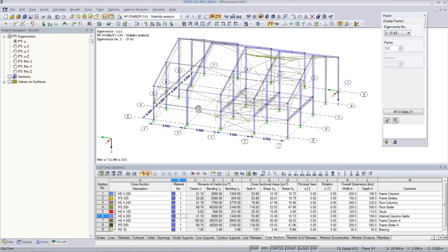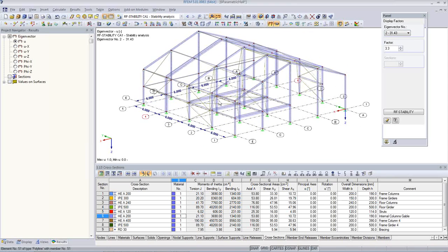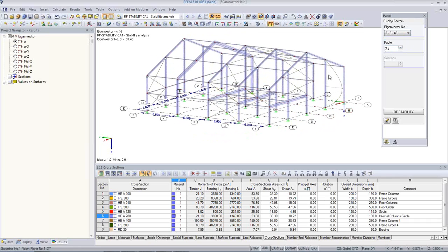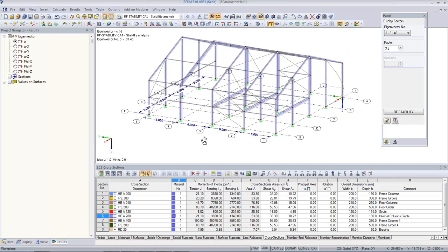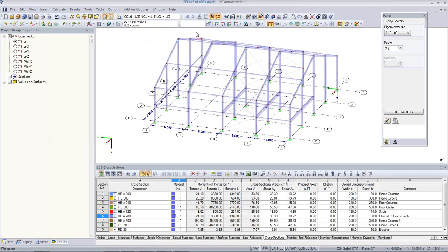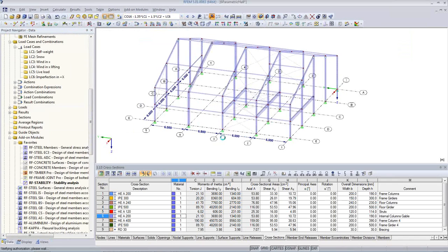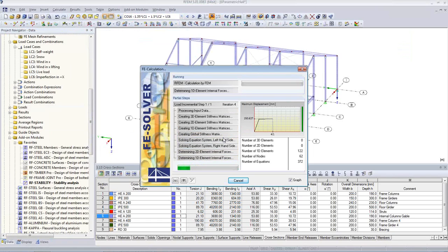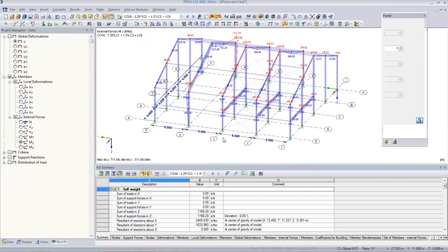Then the other critical load factor is the typical buckling mode of the frames. And the third one, now here we have this column. So at 31, so before it was some 10 times lower, the load factor is now higher by increasing those columns. And now I can try if I can also do my second order analysis. So I run this load case 16 and get my results, and now there should be no more problem.